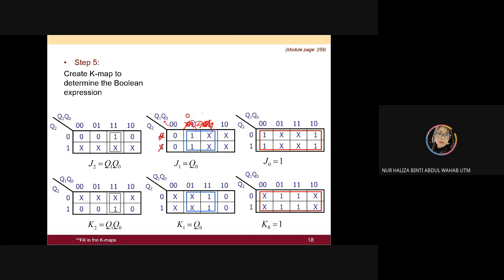If the fixed values here are 0, 0, and then here maybe 0 and 1, you pick this as Q1, but it is barred. This is your K-map thing. I hope you still remember. Last time it was A, B, C, but it is totally similar; these are variables also. For this part, you can see this one is fixed: your Q0, Q1, but your Q2 changes 0 and 1. That's why you ignore that. Your answer is Q1, Q0.